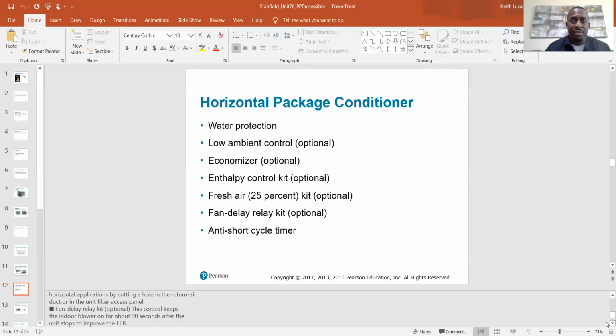Some account for that. When they put in a fresh air intake, they put in a bird screen or put a filter on it, or it'll be a unit where the filter is installed in the unit itself. I've seen that not be the case. Like I said, the filter was down inside the building in a return grill, and then the fresh air was up on the roof in the exposed portion of the return, and that coil was very dirty. Bird feathers, twigs, and weeds, and all types of debris, because it's sucking everything in. As the wind blows, whatever that wind's blowing across the roof is getting sucked into that fresh air intake and then getting jammed into the coil. So for fresh air kits, if you're putting one in, use an actual kit, like the professional kit, and make sure it's all filtered and installed correctly so you don't ruin your coils.